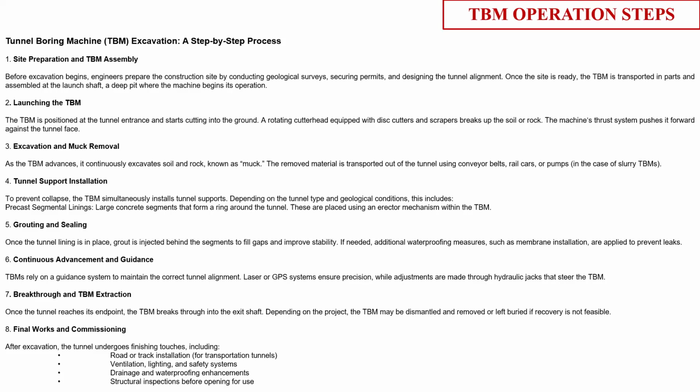In metro projects, if you compare Delhi, Pune, Bangalore, Mumbai, generally, if you compare both shifts, we install around 15 to 20, sometimes 10 to 15 rings per day. Now, once the TBM starts working, it is not continuous. If it is a 3 kilometer long stretch, the TBM will work through it. There will be intermediate shafts also, or intermediate removal of the TBM for the maintenance part, or for the intervention part also.